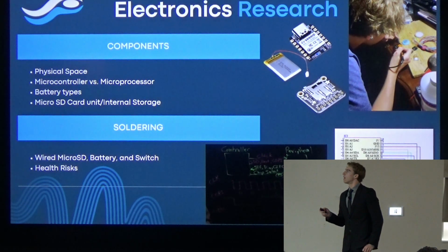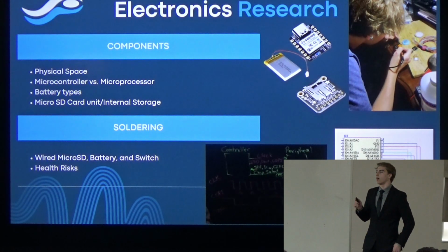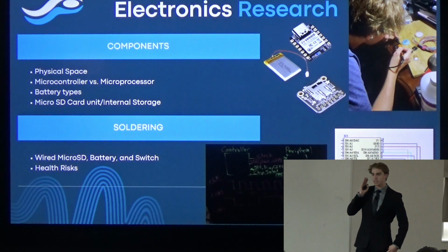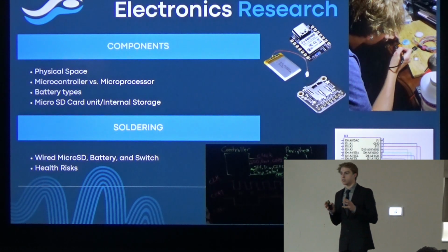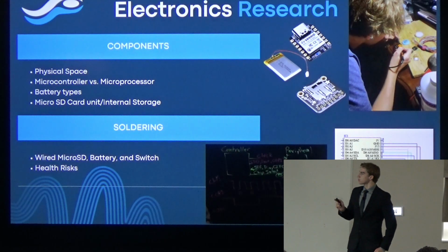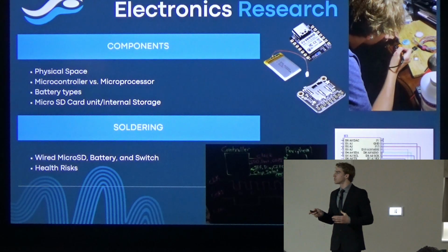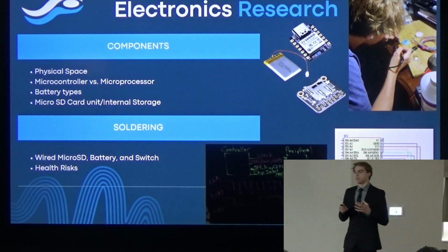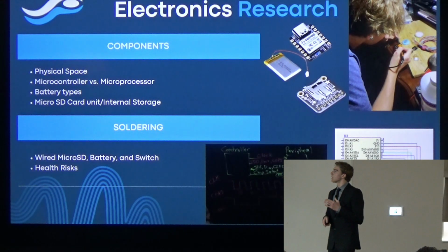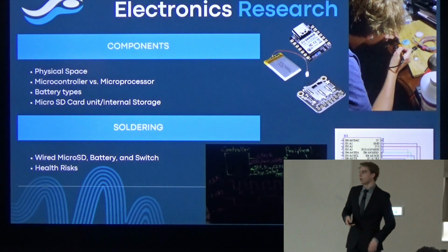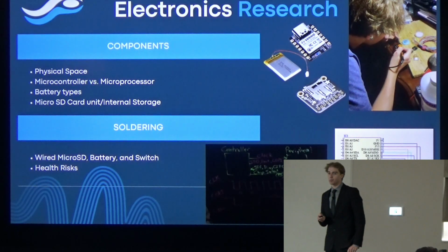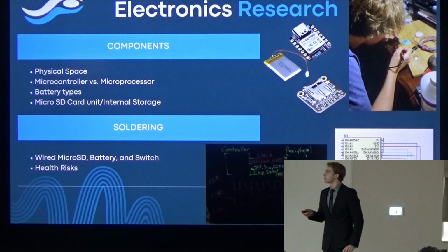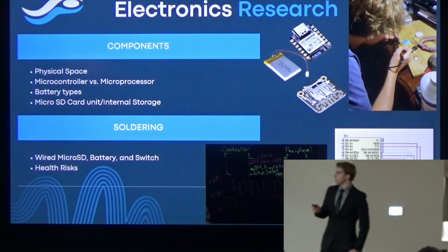Physical space for the components was a huge consideration, because I wanted this device to go inside the cap of the swimmer, so it needed to be small and comfortable. I initially began with the microcontroller, which needed to be very small. Additionally, it is different from a microprocessor. I found that out because I was going to work with a Raspberry Pi, which has way too much processing power and drew way too much power from a battery. So the microcontroller was much more effective for this project.